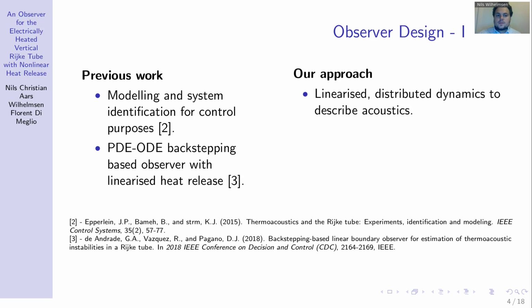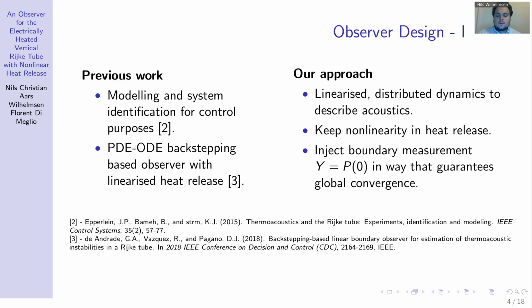For the approach considered here, we also use a linearized PDE model for the acoustics. However, we decide to keep the nonlinearity in the heat release, so these important nonlinear dynamics are not lost. Our design approach can be summarized as injecting the measured pressure from the lower boundary in such a way that global convergence can be proven.